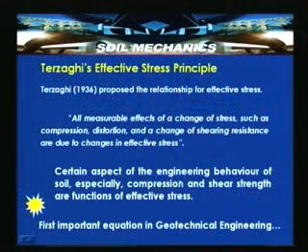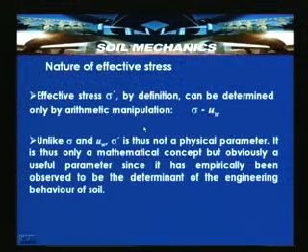So, we have introduced Terzaghi's effective stress principle, and now we are looking into much more detail about this concept. Effective stress sigma dash, by definition, can be determined only by arithmetic manipulation, that is sigma dash is equal to sigma minus UW. Unlike total stress sigma and pore water pressure UW, sigma dash is not a physical parameter.